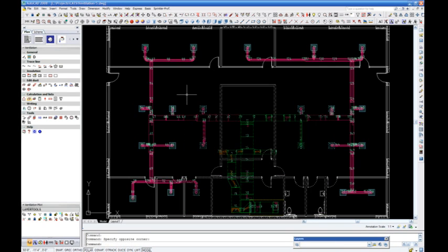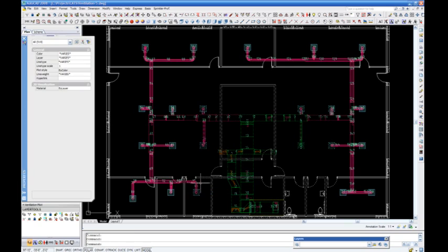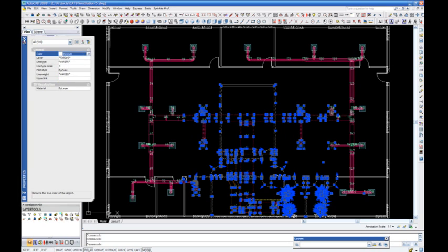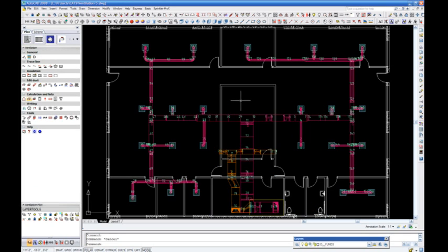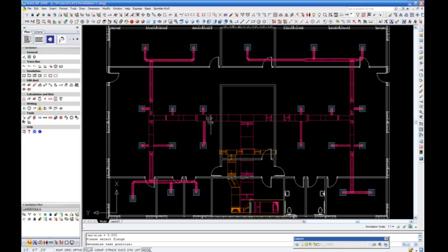We will now restore the drawing's original characteristics. The position numbers layer from the pressure drop calculation is turned off. In the C.A.T.S Commander, we will dimension the duct sizes by clicking on the duct flanges or the sides of the round pipe to show each dimension.